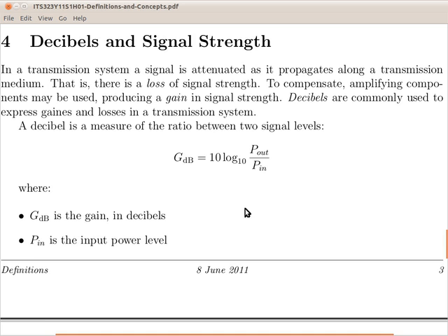That's the absolute gain. The gain in decibels is 10 times log, sorry, maybe to make more clear, this is logarithm in base 10. 10 times log of the absolute gain. Log in base 10 of 100 is 2 multiplied by 10, 20 decibels, 20 dB.